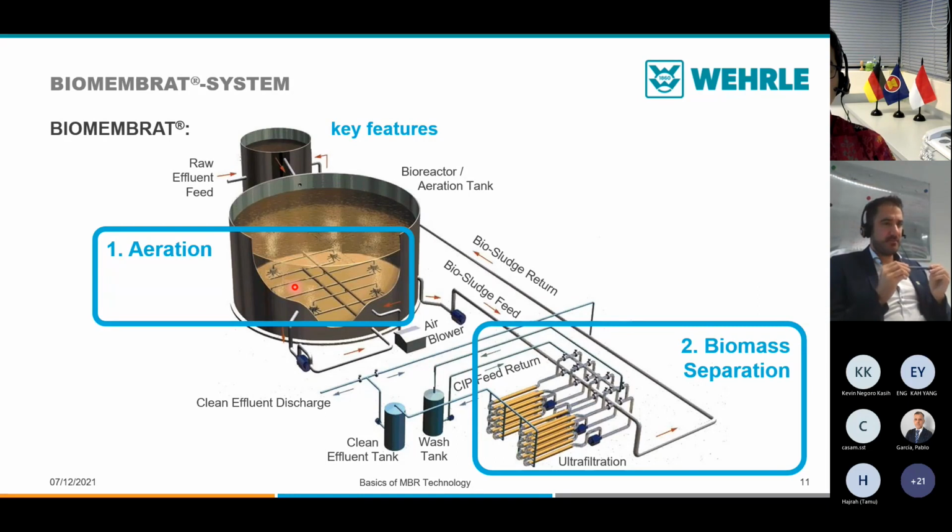That is quite important. Those jet ejectors get installed and they last up to 25 years or longer in the tank. Think about if you have a big plant with, let's say, 2000 cubic meters of aeration tank, and you need to replace your aeration system like a membrane diffuser because it's clogged or cracked, and you have to discharge 2000 cubic meters of activated sludge. That is a really big problem that costs a lot of money, and that will stop your production.